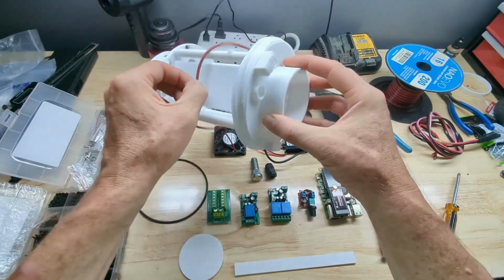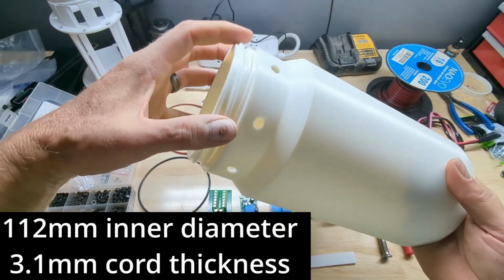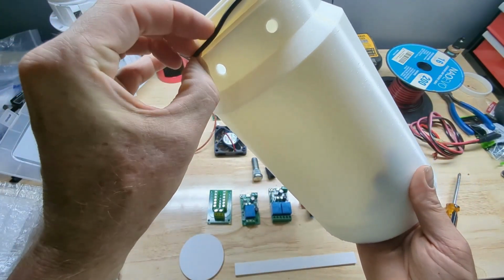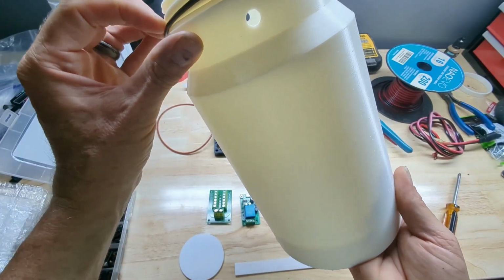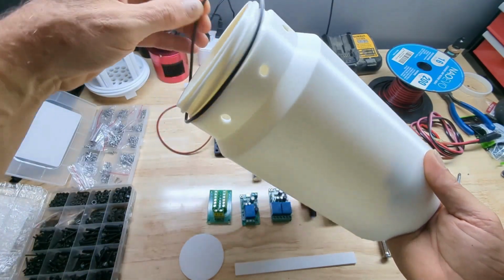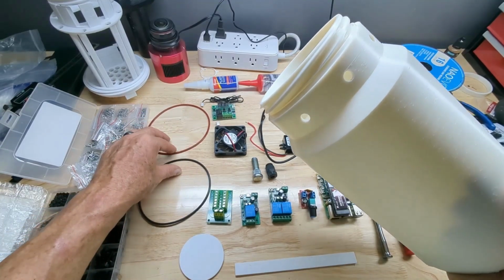Now, this top one, this black one that we have here, actually goes on the top of this enclosure. So when you put your dome on, you screw it down, it'll seat tightly to that. So both these rings, the top O-ring, the cap seal that we'll call it, is a 112 millimeter inner diameter. So it just sits on this ridge, and when you put the cap down, it seals tightly on that. The thickness of this cord is 3.1 millimeters, but I will have parts linked to these that you can buy directly on Amazon.